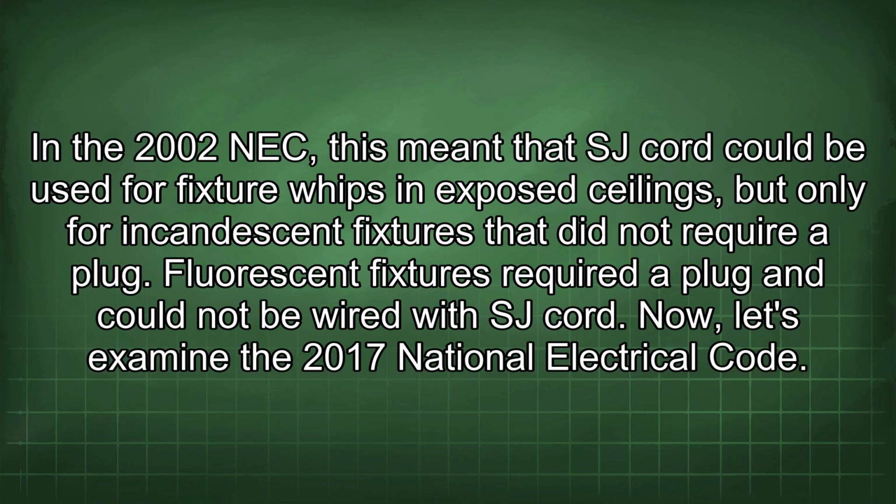In the 2002 NEC, this meant that SJ cord could be used for fixture whips in exposed ceilings, but only for incandescent fixtures that did not require a plug. Fluorescent fixtures required a plug and could not be wired with SJ cord.